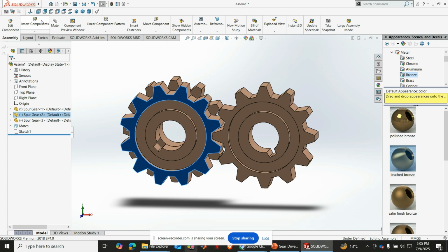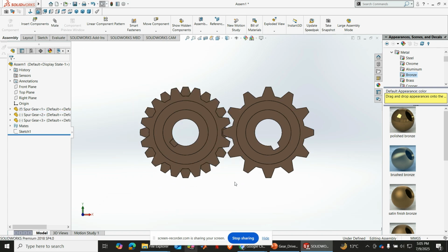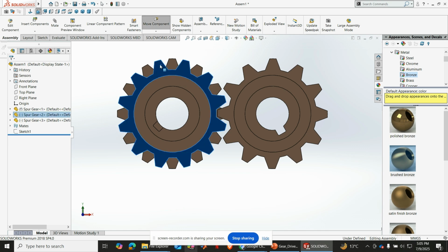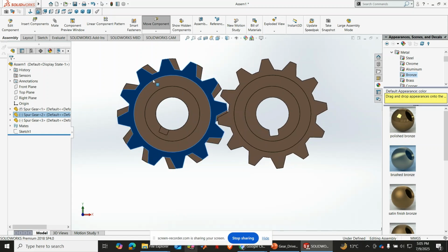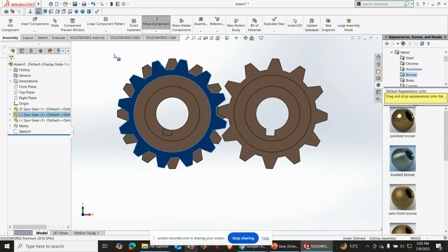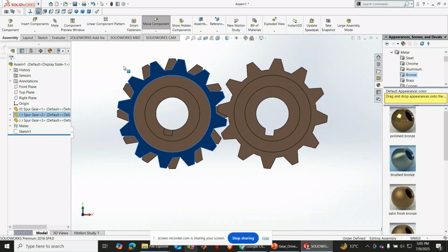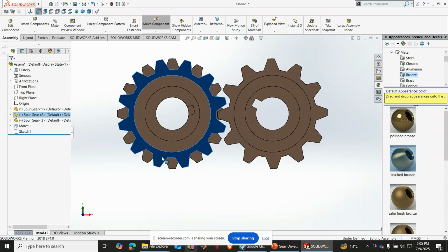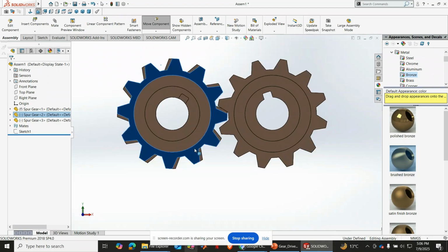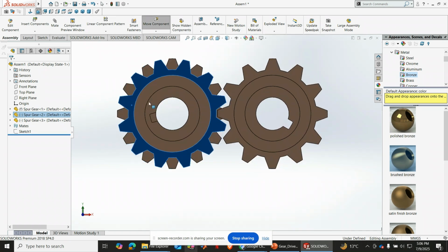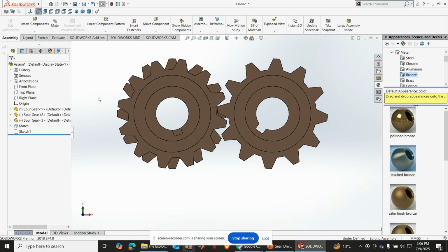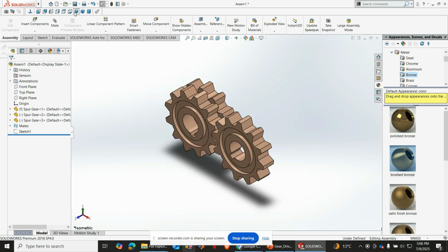So you see, your gears, and as you can see, like this, the gear rotates like opposite, not in the same direction, in opposite directions. So what if we want to have the motions in the same direction? That means we need a gear in between these two. So we can make this an idler gear, which is between the gears, and we can position another gear here, or we can position on this side, right? We can position another gear on this side. Okay, so let's do that.